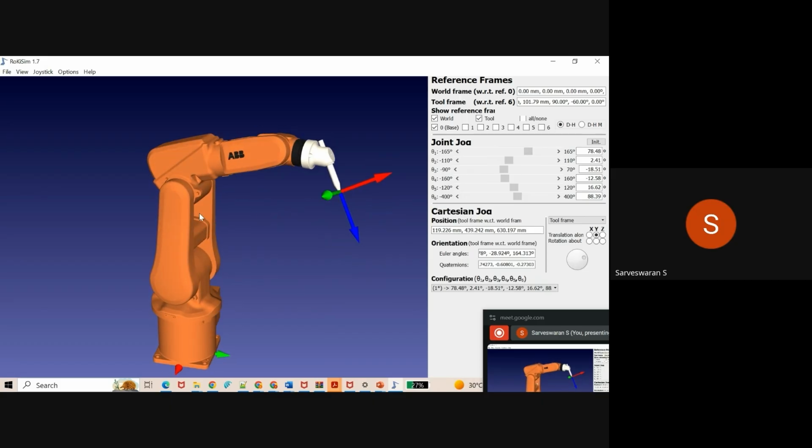Joint 1 has to carry the entire robotic arm, and it has to move or overcome the torque that is generated considering all the link lengths. You have to consider links L1, L2, L3, L4, L5. Self weight also you have to consider. All the robotic links are rigid links, so you will have a very high load, and also a payload capacity.